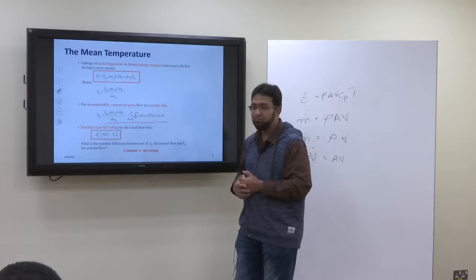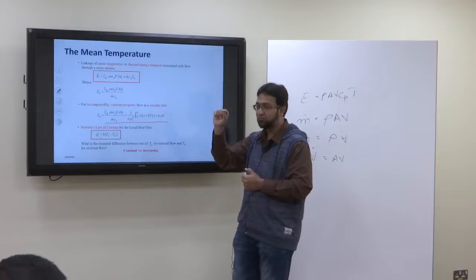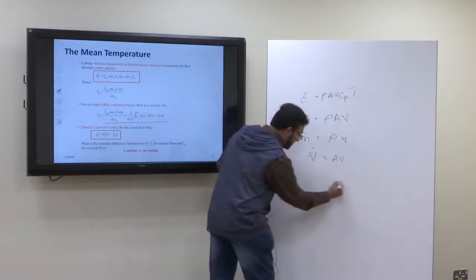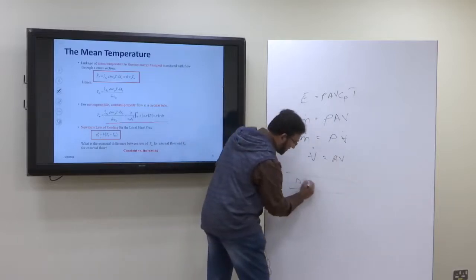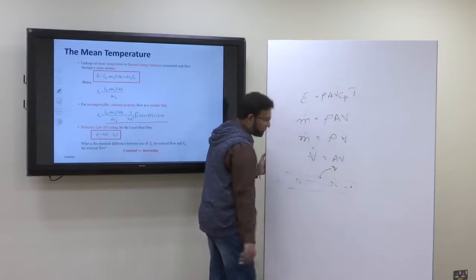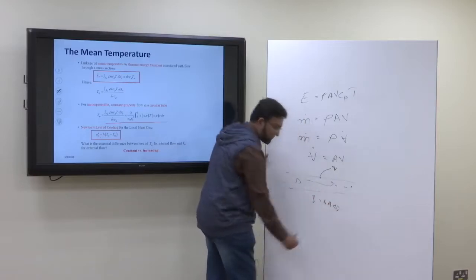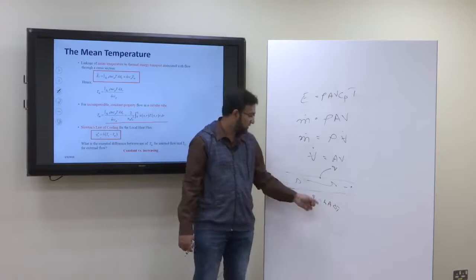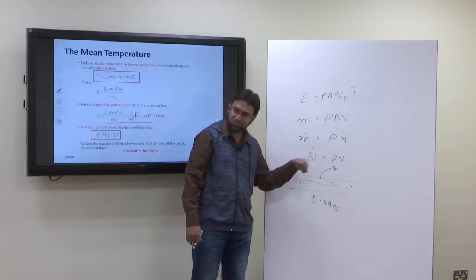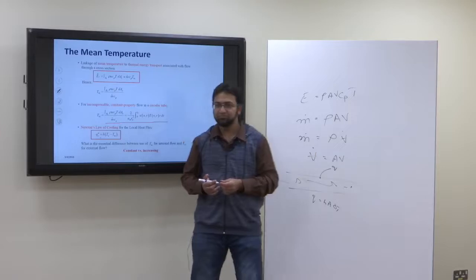So at any specific point, if you want to know how much the heat transfer is, say you have a pipe and the flow is going through it, then Q is equal to hA delta T, where delta T will be the surface temperature minus the mean temperature, or the mean temperature minus the surface temperature, based upon in which direction heat is flowing.